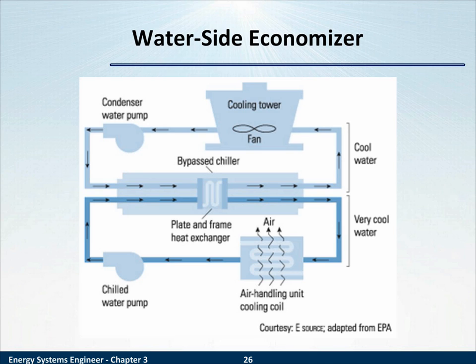We introduced the term economizer to mean either an air side or water side economizer. Air side being utilizing cool, dry air from outdoors, bringing it into your space to cool the space without conditioning. A water side economizer utilizes the existing chilled water system, but in a new and interesting way. With the two loops, condenser water and chilled water, still being separate, but connected through a heat exchanger.